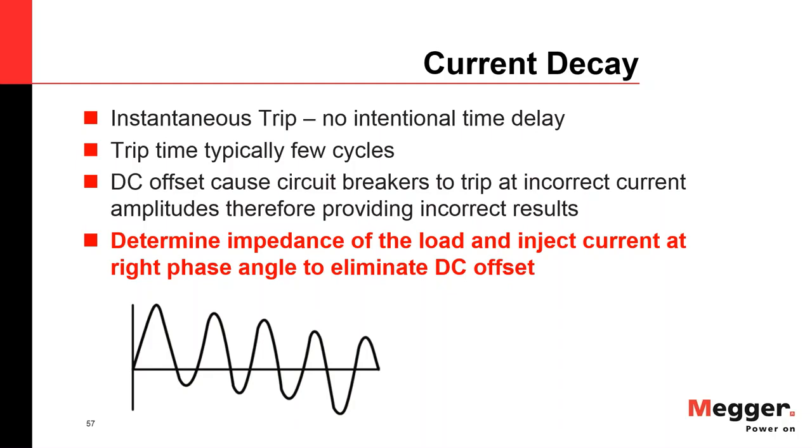On a symmetrical waveform, these two numbers are the same. If you measure the true RMS and you measure the peak and divide the peak by √2, that should be the same number. If you have a fairly asymmetrical waveform, these two values are not the same anymore.